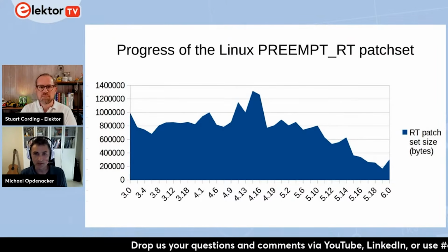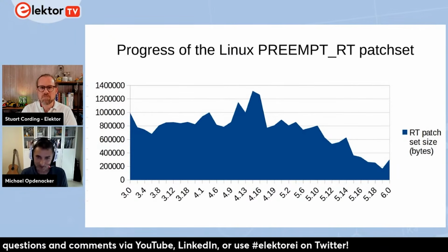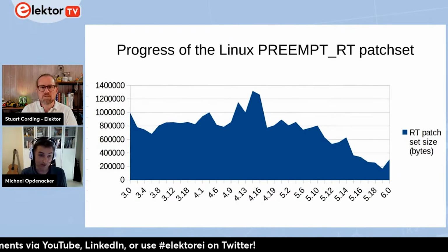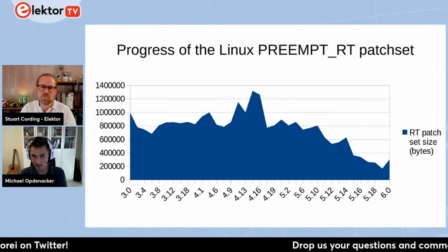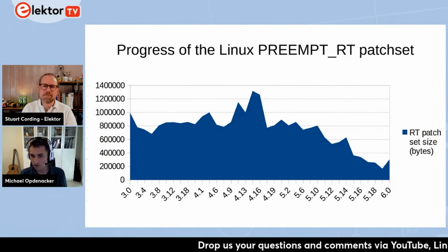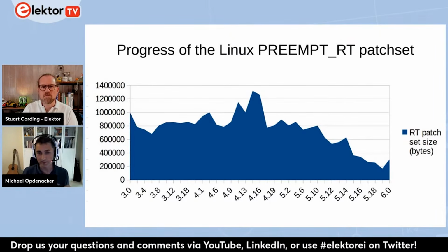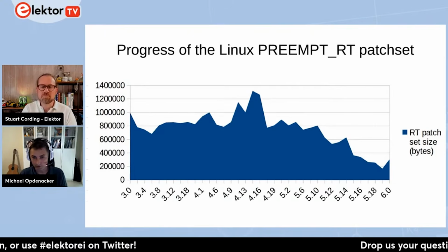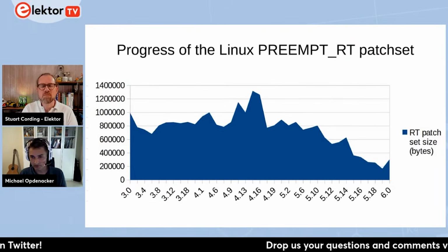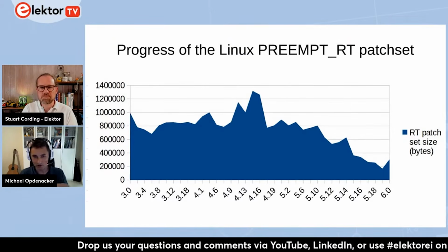That's the worst case, like when you start reacting to the event. This being said, the infrastructure is getting much better now, and you could use other projects that are even better but more complicated, like Xenomai. Xenomai adds a real-time kernel between Linux and your hardware, so the real-time applications are really handled by a real-time scheduler. You can divide the worst case reaction time by 3 or 4, but it's more complicated to support. Not all hardware is supported. So these are the low level solutions.